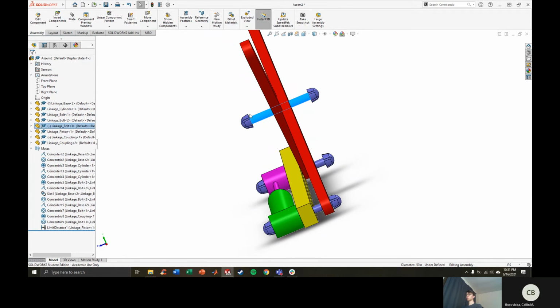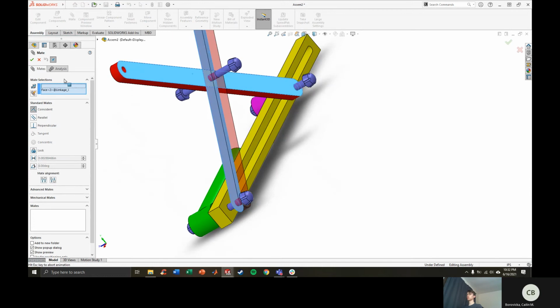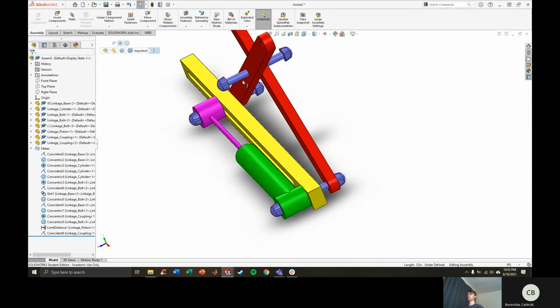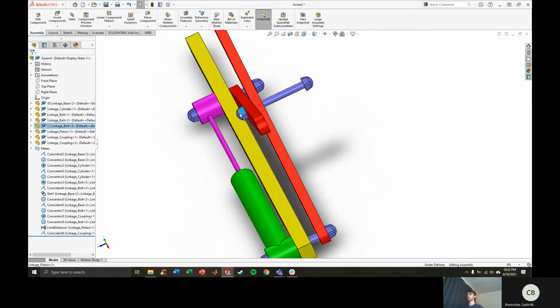And this was say 1 millimeter longer than the distance between these two faces, which are not constrained. I wouldn't want to necessarily just mate the one face of the bolt to the one face of the link like we had, because then there's all this excess on the other side. Really, it's supposed to be in the center.